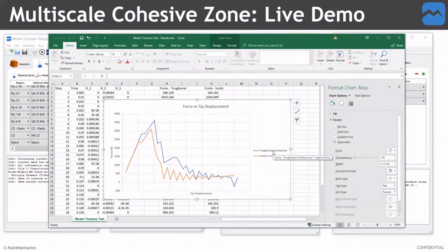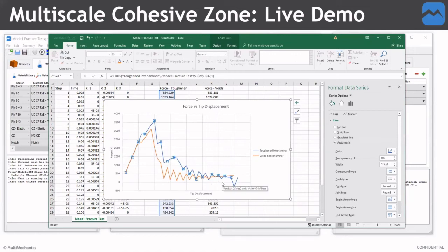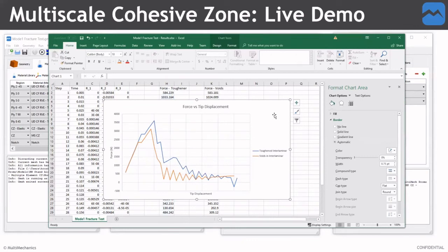models. First, the interlaminar toughened one has a little higher stress at break, and we can see that in general, if you take the area under this curve, we have more area, which means more fracture energy. So it's a much tougher interface. So you can run different, say, volume percentages of particulates to see how exactly you can predict the increase in fracture toughness. You can also look at the difference in, for example, voids to gauge how changing your manufacturing process could negatively affect your interlaminar properties within your composite.